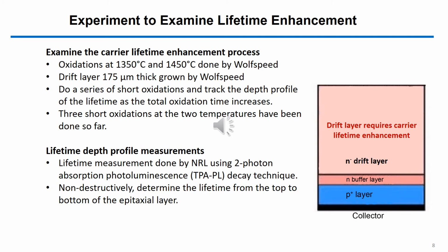We have started experiments in collaboration with Wolfspeed. Wolfspeed is providing the epitaxial layer, which is 175 microns thick, and they are also doing the oxidations at 2 temperatures, 1350 and 1450.